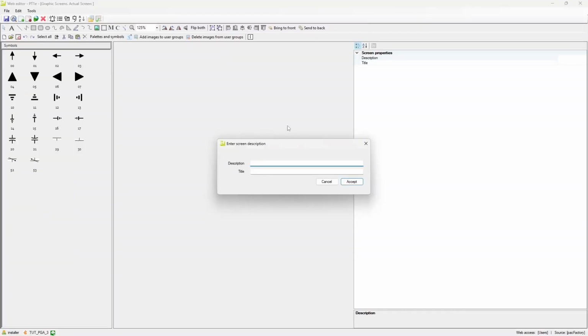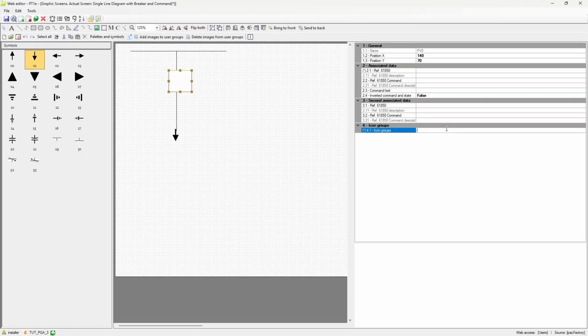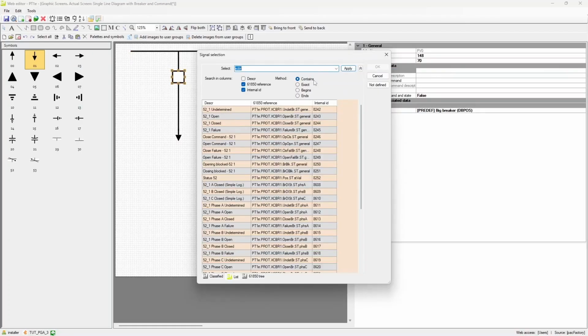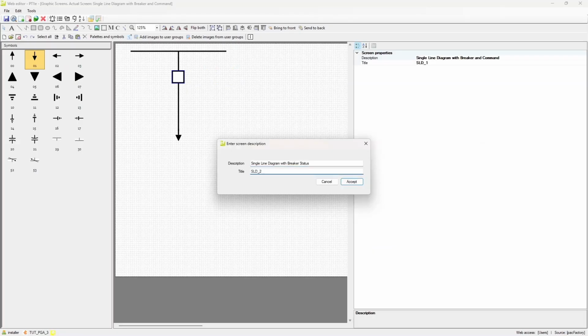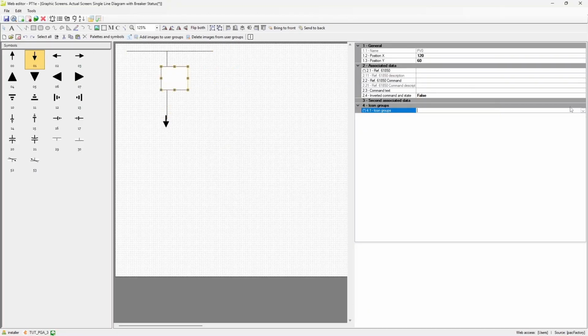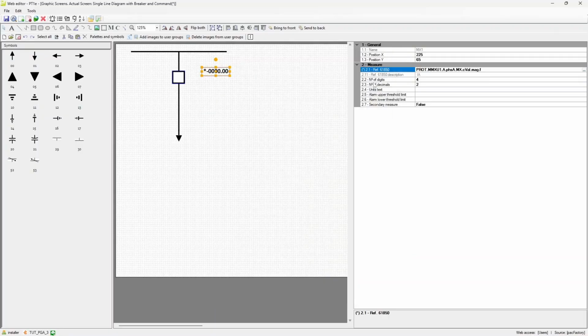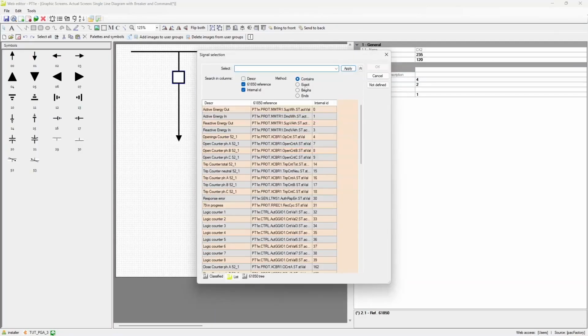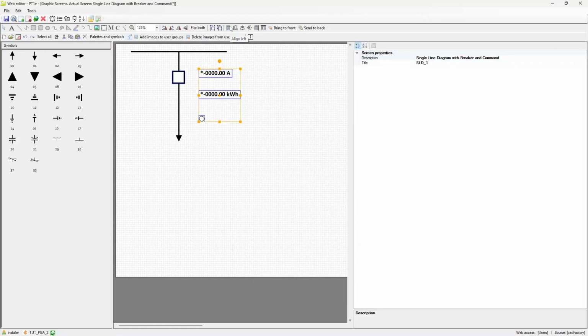column. Initially, we will set up a simple single-line diagram featuring one bus bar and one breaker. This breaker within the SLD will be controllable. Next, we will create another single-line diagram with the same breaker, but this time it will not be controllable. Similar to the local display editor, these web displays allow us to configure measurements and counters, as well as active elements like disconnectors and indicators.